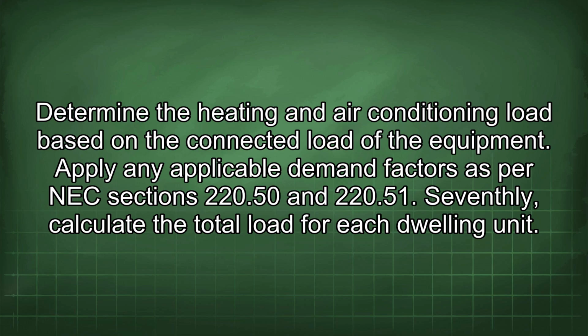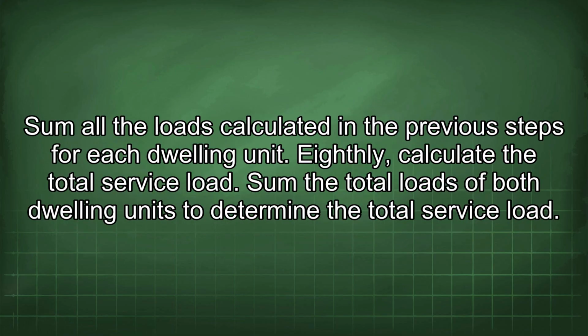Apply any applicable demand factors as per NEC sections 220.50 and 220.51. Seventhly, calculate the total load for each dwelling unit. Sum all the loads calculated in the previous steps for each dwelling unit. Eighthly, calculate the total service load. Sum the total loads of both dwelling units to determine the total service load.